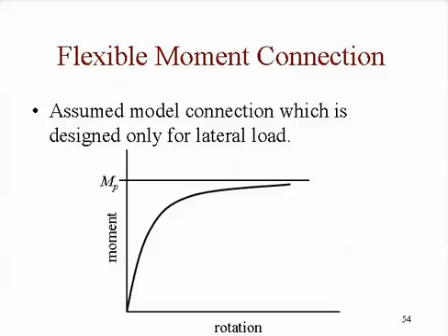And we run into trouble when we use some of the model equations because, as I said before, and like on that picture, if you don't pick up the fact that you get to a point and one of the bolts fail or some other limit state occurs, if you get too far out there, you're not going to have the behavior that you expect. So we're looking at a connection here that's going to have a plastic moment capacity as its ultimate strength.